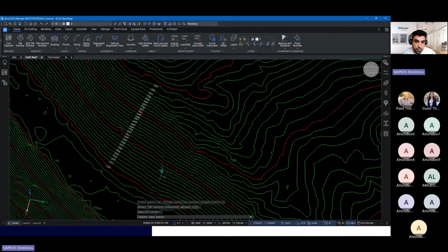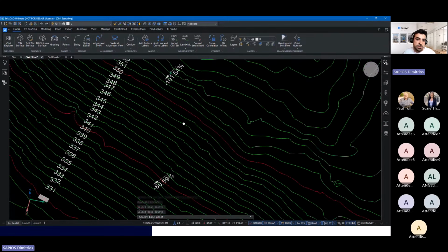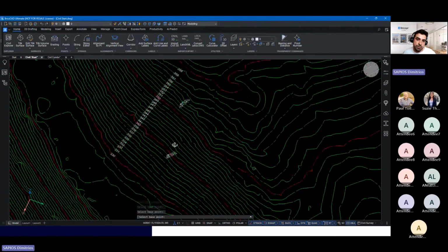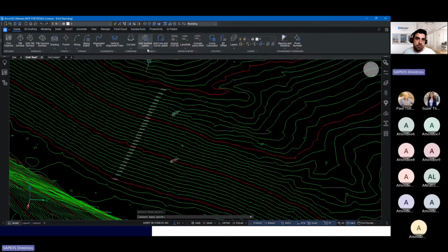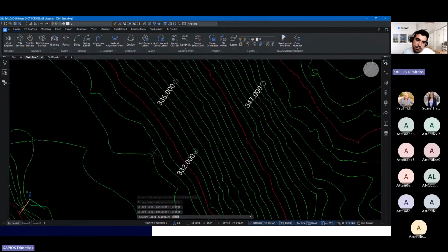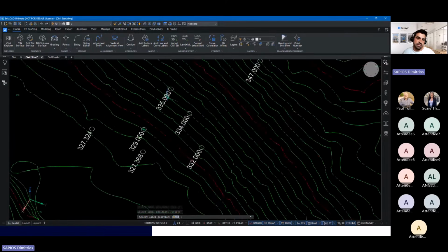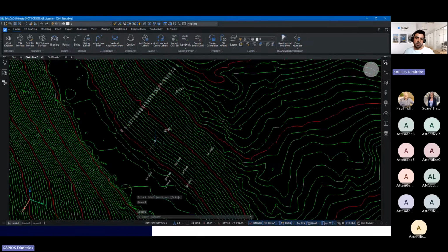And in the exact same way, I just click on a point, and it will give us the slope in percentages. And on a final note, we can quickly add spot elevations in our tin surface. Selecting the tin surface again and just clicking gives us the elevations by using a specific block within the drawing. So all those options and labeling styles can be changed.